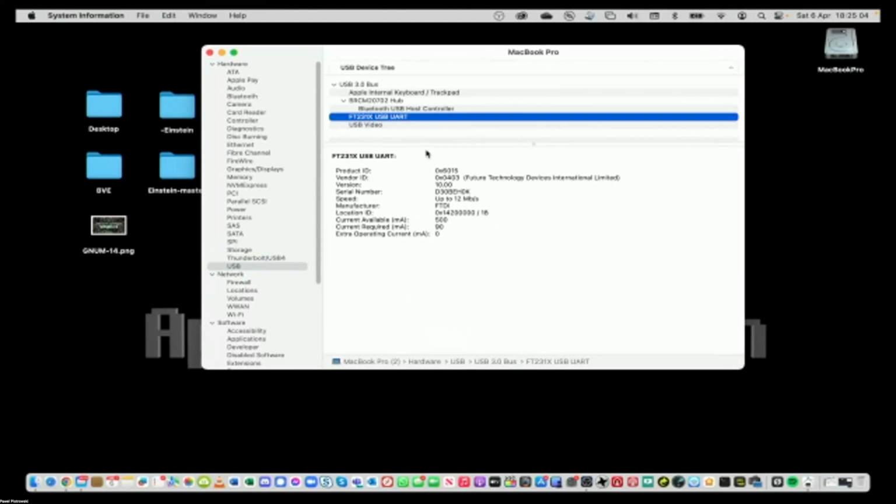So this chipset, for example, reports as a FT231X. The important thing is that it must be an original FTDI chipset, not any other controller, and that's it. So if you manage to find that kind of cable with that kind of chipset, it's 99% that it will work.